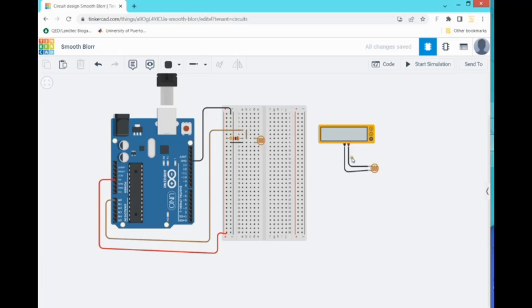The only thing that I need is to understand a little bit better the photoresistor, and for that, since I know that the photoresistor will change its resistance value according to illumination, let's do a quick test using a multimeter, but the multimeter has to be set to measure resistance. With that said, we start the simulation. There's no code here, so I'm not doing anything.